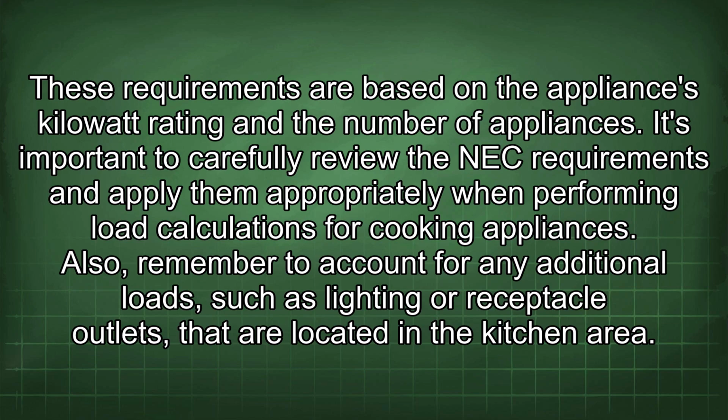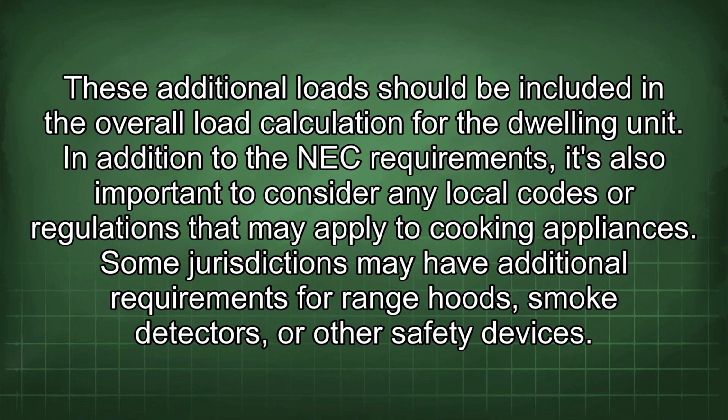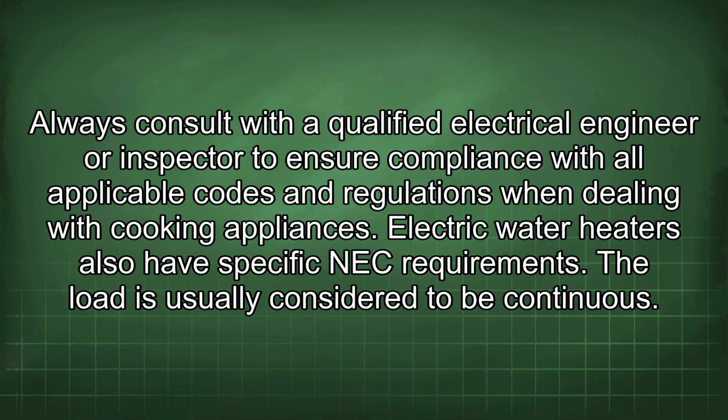Also, remember to account for any additional loads such as lighting or receptacle outlets that are located in the kitchen area. These additional loads should be included in the overall load calculation for the dwelling unit. In addition to the NEC requirements, it's also important to consider any local codes or regulations that may apply to cooking appliances. Some jurisdictions may have additional requirements for range hoods, smoke detectors, or other safety devices. Always consult with a qualified electrical engineer or inspector to ensure compliance with all applicable codes and regulations when dealing with cooking appliances. Electric water heaters also have specific NEC requirements.